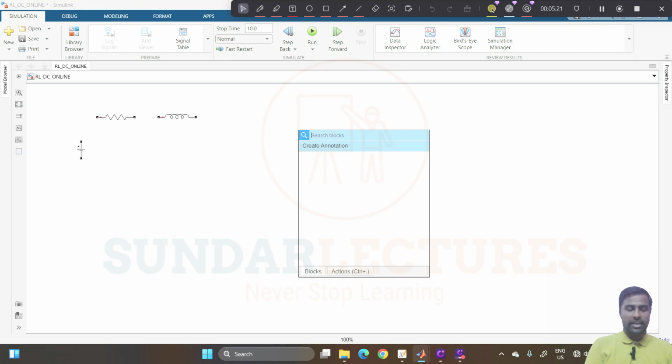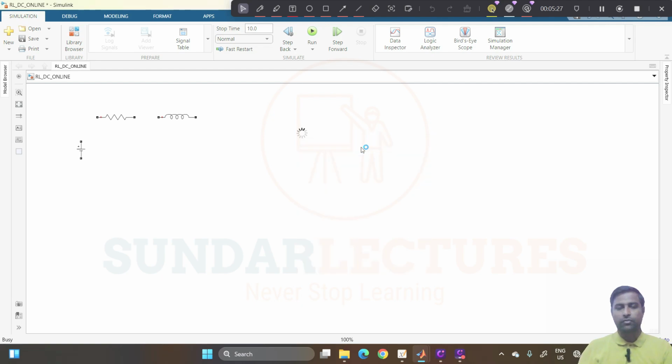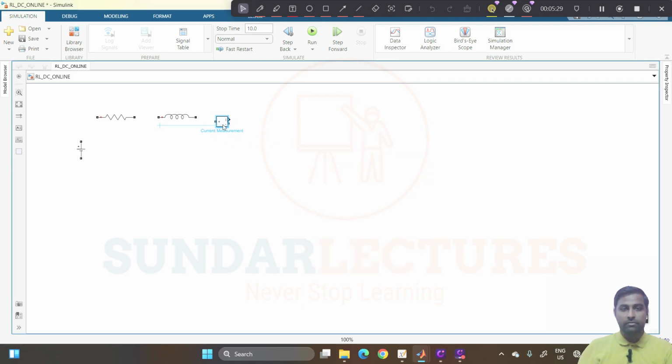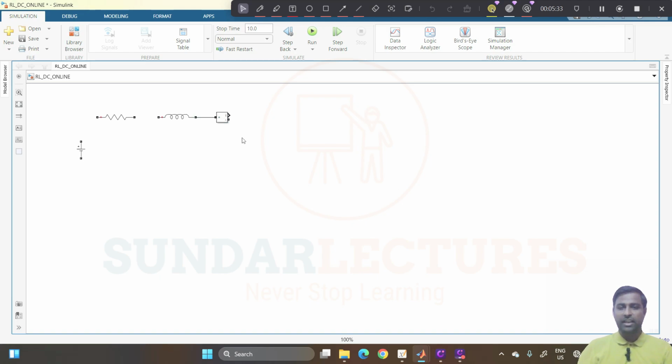Now this is the circuit and we need to measure current as well as voltage. So you double click at any place and type current measurement. See, you are getting the current measurement here, or you type it out fully. You just keep this here. It can be connected like this, or you can use wires to connect. Like this also you can connect, no problem.